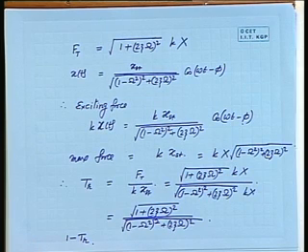So, basically what has been done is that in the handbooks you will find mount deflection plotted in terms of frequency ratio, and then for a particular frequency ratio, for a particular isolation, what should be the mount deflection.